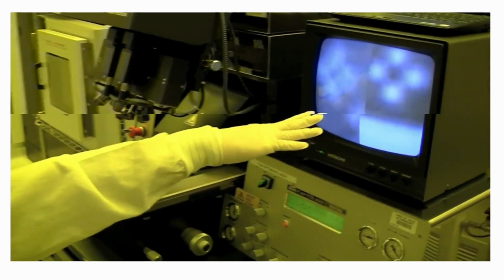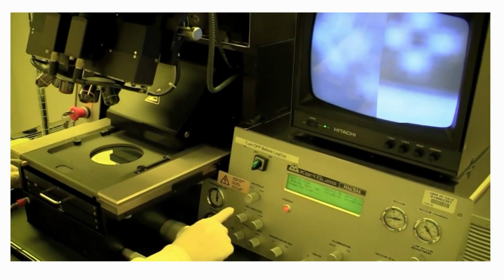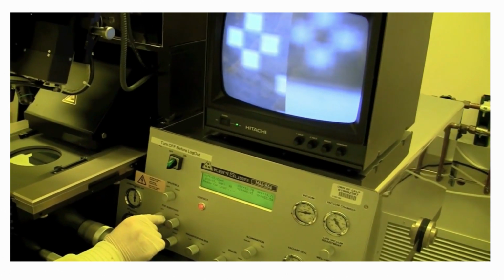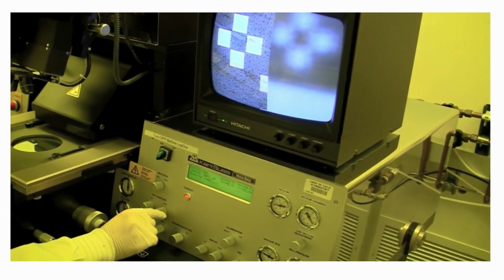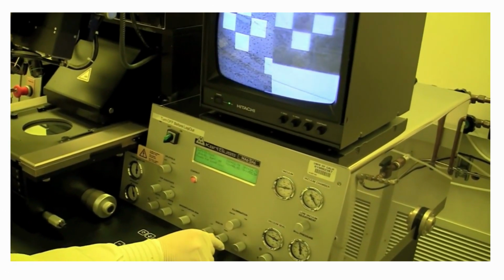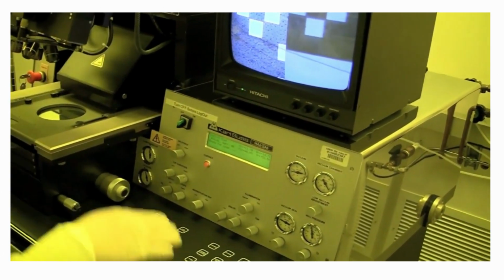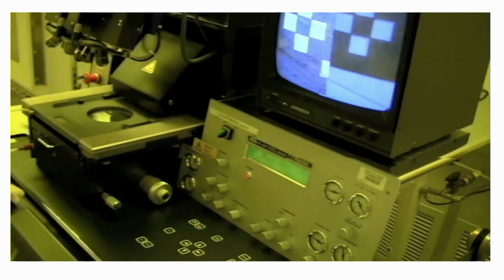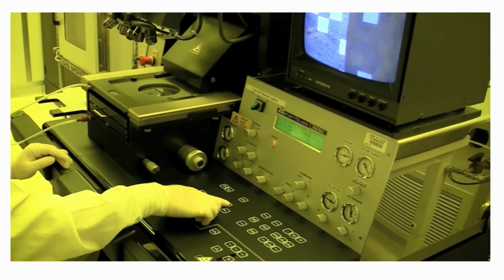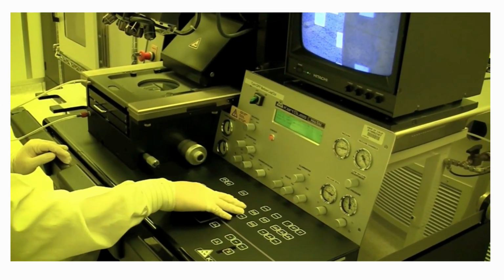It looks like we found alignment marks on the mask. So we need to adjust the focus. So you use this top straight left and right. So the left one adjusts the left, and the right one will adjust the right focus. You can also adjust the intensity. And you can also adjust the position. So if I want to move this one up and down, I will hit right, and then I would move it up and down. If I want to move the left one, it's a similar thing.